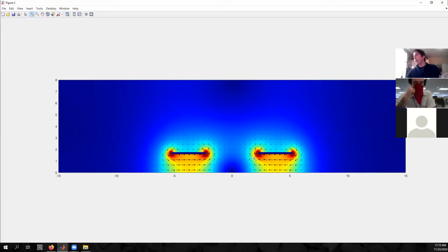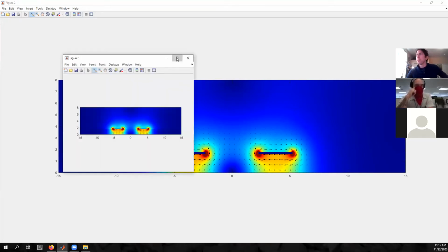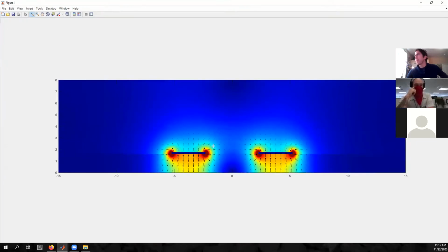You then do the same sort of analysis where I can calculate, say, the total magnetic field energy here, or the total electric field energy, or you can do a number of different approaches. I need to calculate the equivalent capacitance and inductance here. So I need to calculate the total charge on that strip and calculate all the flux coming through by doing the flux out of it. Or you can calculate the total electric field energy in this entire system. Both of those methods will work, just there'll be a few percent difference between them depending on the precision of your model.